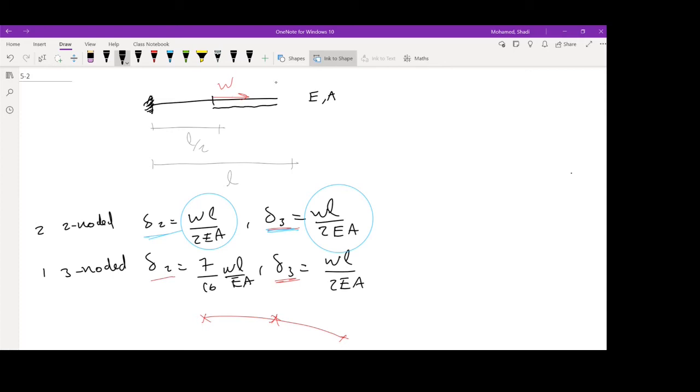Starting at the midpoint, you have a force active on your cross section A, and this is going to be your stress. So the force is W. From this point onward, the stress is going to be W divided by the cross section, and it is going to be constant for the rest of this length. So the stress would look like this: a constant value up to the mid length, and then 0 for the rest of it.